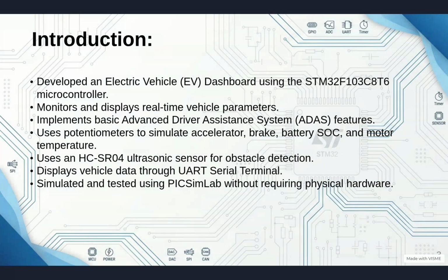We also integrated an HC-SR04 ultrasonic sensor to detect obstacles for the ADAS feature. The processed vehicle data is transmitted through the UART and displayed on the virtual terminal. Finally, we tested and validated the complete system using SimLab without requiring physical hardware.